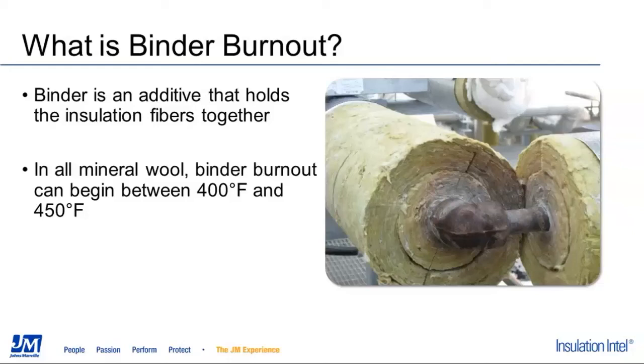Also, this picture, I just want to point out for those of you who install insulation all the time, is actually an example of how not to install the insulation because the joints are not staggered, but it is still nonetheless a good demonstration of the binder burnout.